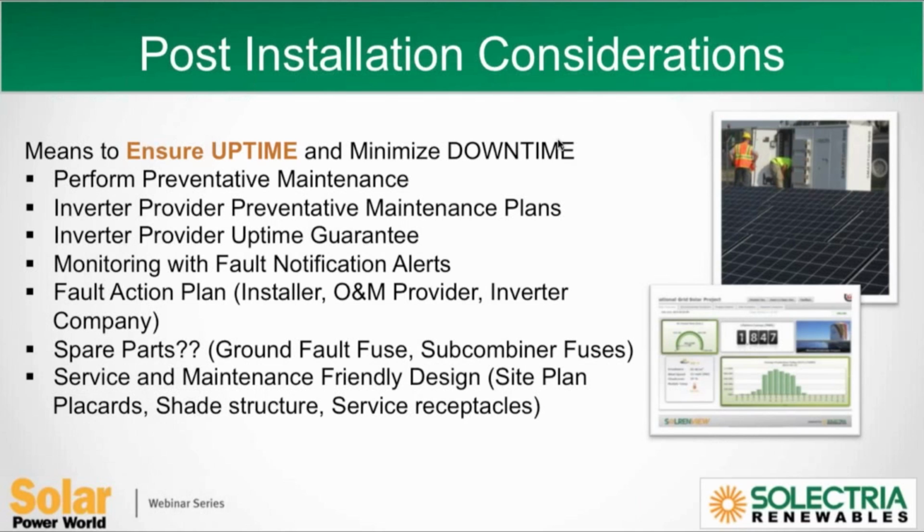Something you don't want to question is preventative maintenance. Just from my experience working in the field and with field engineers, preventative maintenance is one of those big opportunities that customers a lot of times neglect. We don't want to give the impression that PV is totally without maintenance. You want to have your annual or biannual maintenance checks where you check the torques of the inverters, clean the input vents and filters, and check your communication wiring.